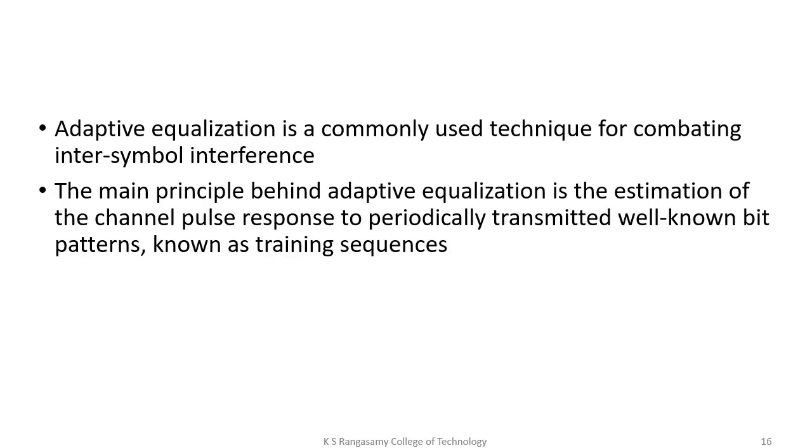Adaptive equalization is a commonly used technique for combating intersymbol interference. We can use the adaptive equalization technique to overcome this interference. The main principle behind adaptive equalization is the estimation of the channel pulse response from periodically transmitted, well-known bit patterns known as training sequences. That is the main concept of eradicating this interference. Adaptive equalization is commonly used to overcome intersymbol interference.